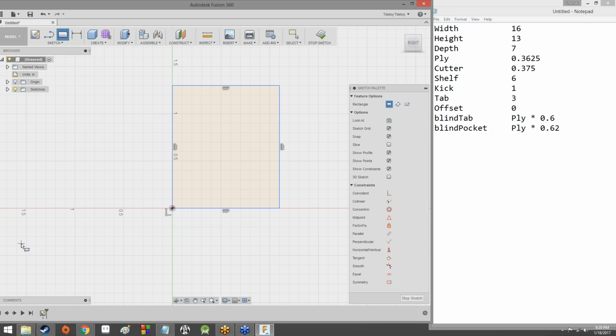Now, there's 2 sides to this. They require that, but sketching and then dimensioning things will also ensure that whatever you make will be exactly the dimensions you want. If you draw something and then you dimension it afterwards, the drawing will resize itself in order to make sense with the dimensions that you were using.